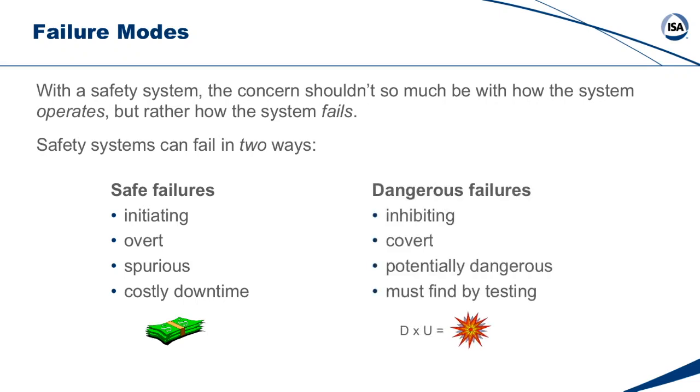SIL, safety integrity level, is a measure of PFD, probability of failure on demand. So it's the idea of the pressure switch is stuck. The relays are stuck. The PLC is hung up in an endless loop and is stuck. The I/O circuits are stuck energized. The solenoid is stuck. The solenoid works, but the valve body is stuck. These are all dangerous failures.